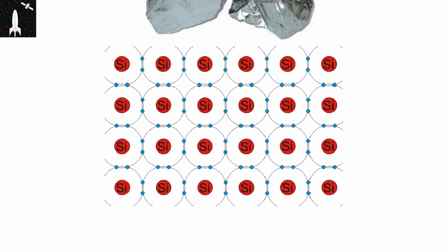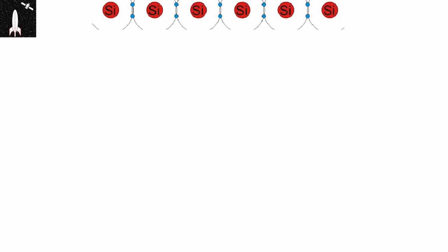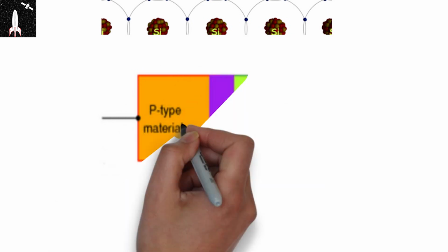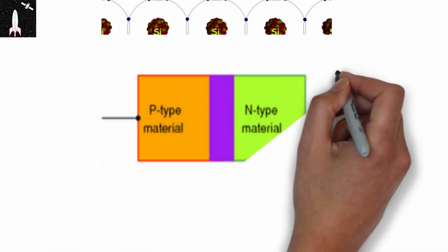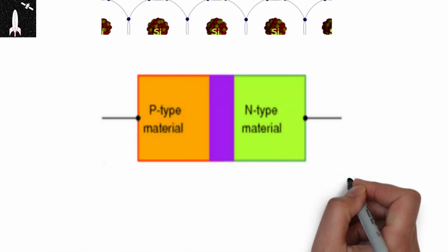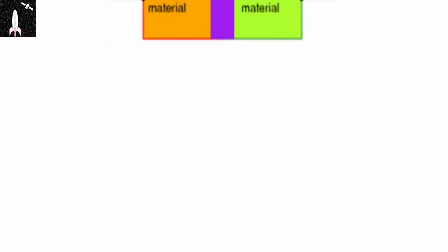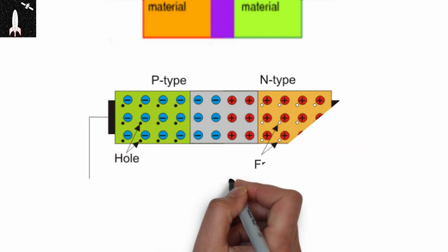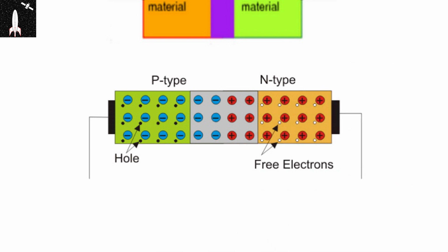As discussed in our earlier video about transistor, we saw that pure silicon doesn't have any free electrons. However, we won't be using pure silicon. We will add impurities to it. This process is called doping. One part is doped with N-type impurity while the other is doped with P-type impurity. Once the doping is done, at the N side we will have free electrons, and at the P side we will have vacant holes for the electrons.